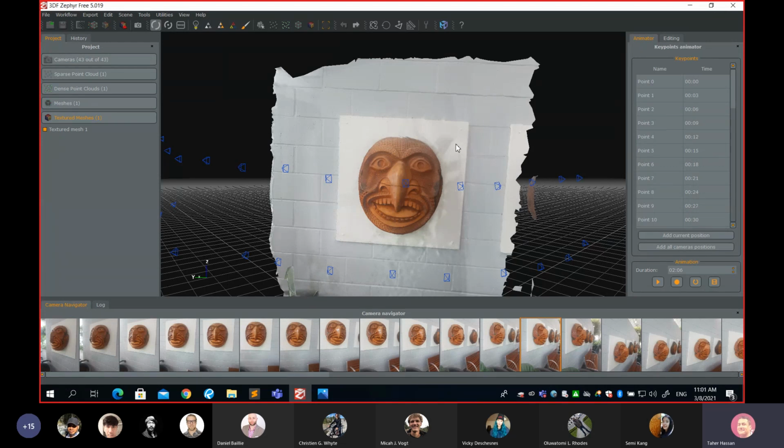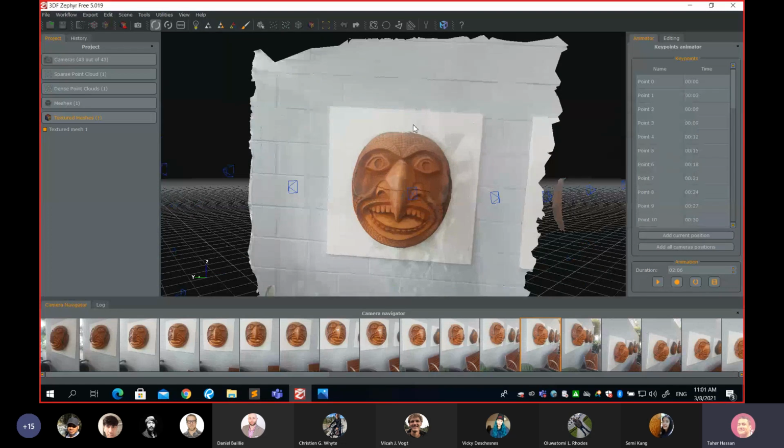However, it's not a big deal. By the way, it's not a big deal because all you can do is go to the Devonian Garden, if you can do it right now, and measure a distance from here to there, and then you can simply scale the entire 3D model by the same scale. For example, if that's 14 units here, and this happens to be 30 centimeters or 50 centimeters, you can find the scale, and then in this software, you can scale things up or down. Are you following? Yep. So when you create a 3D model with photogrammetry, it lacks the scale. That's an easy fix. If you measure one distance, you can scale your object up and down.